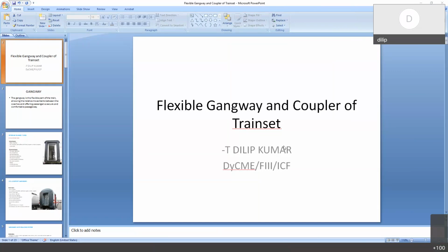Yeah, somebody asked regarding the accident relief train. So this rescue coupler, what we call a rescue coupler, that type of rescue coupler should be made part of the ART trains. That rescue coupler has to be fastened to the semi-permanent head, and a locomotive used to move the train out of the section. The complete train can be moved without any problem.